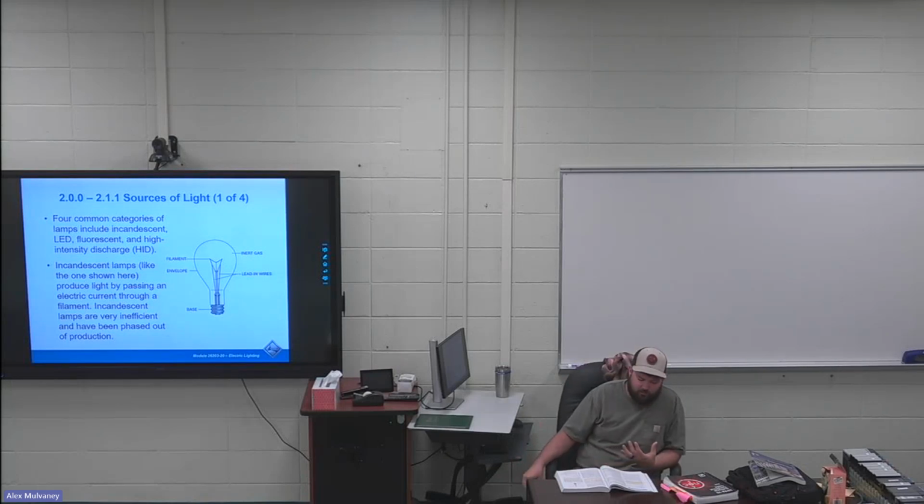So they're pretty important. If an LED light's not working, more often than not, in my experience, I've seen the LED driver be bad rather than the light itself. That's how they can say these lights will last forever. The lights themselves will last a long time, but it's the drivers that are having the problems with keeping working.